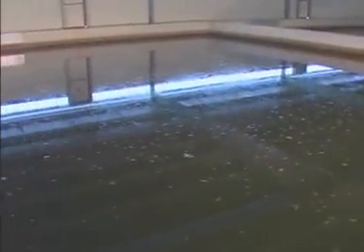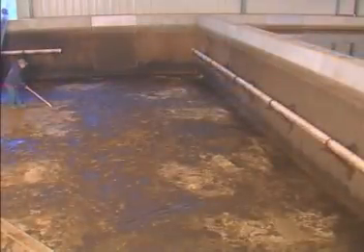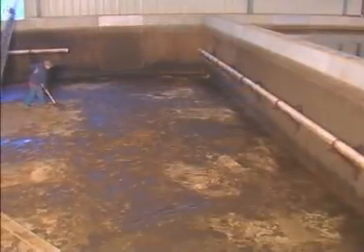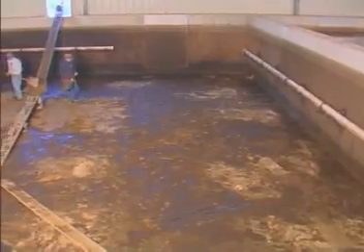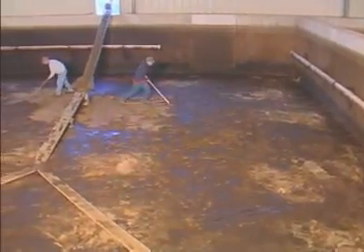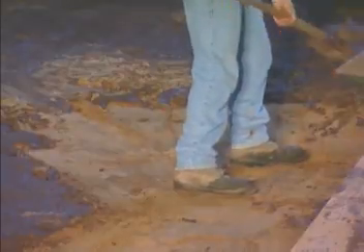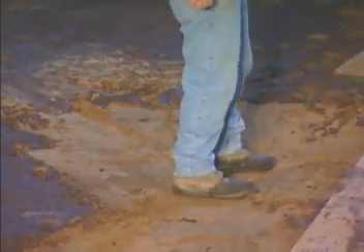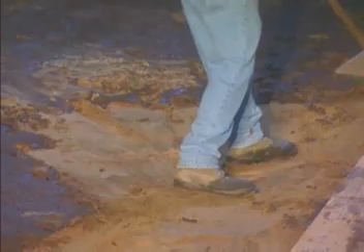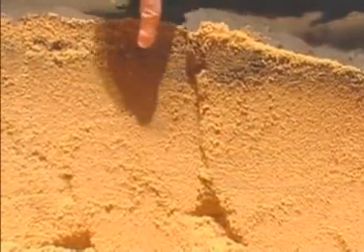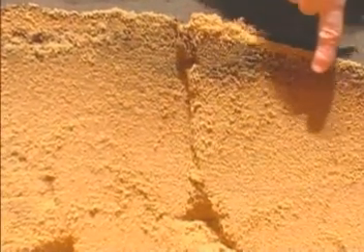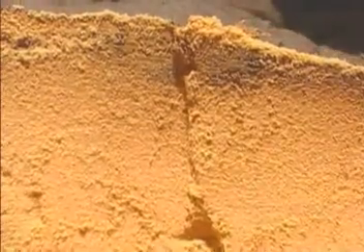Slow sand filters are yet another chemical-free filtration option. The process utilizes beds of sand, normally about 35 inches deep. On the surface of the sand bed, a biologically active layer develops known as the schmutzdecke. This layer provides an excellent addition to the sand media to trap and remove unwanted material from the water.